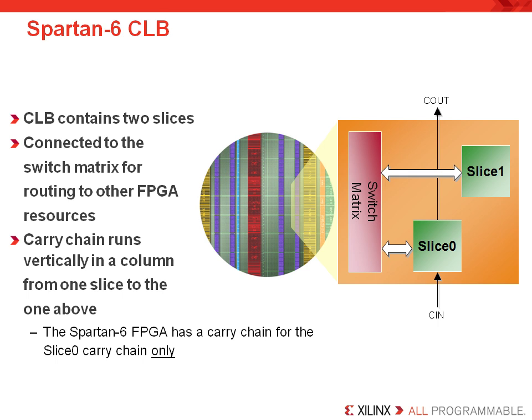Only with some experience can you properly estimate how many slice resources will be necessary for your design without at least synthesizing the design first. The slice resources are the most essential and fundamental to an FPGA design. They include LUTs and registers. LUTs are built to create your combinatorial logic resources, and each has an associated register with it. The LUTs and registers are grouped into slices, which also have other resources.